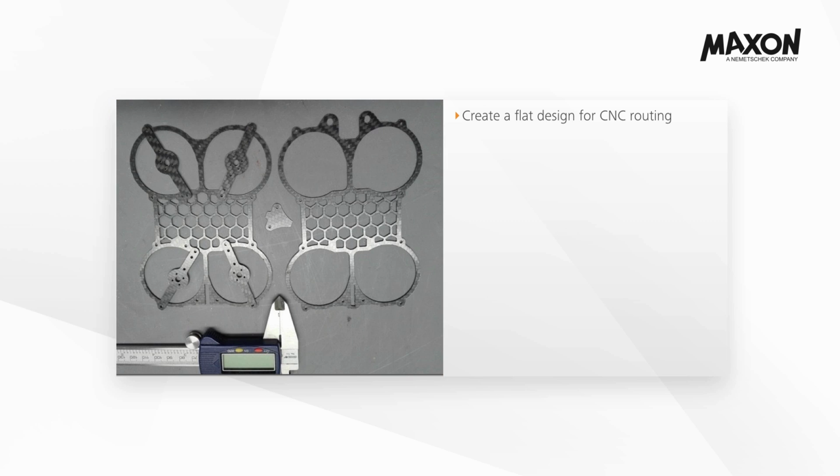So all my frames are made out of carbon fiber sheets, since it is a very durable material, and I contacted several companies to see what a CNC frame would end up costing and what file format they required. And luckily I could use the same 3D model I constructed in Cinema 4D and that I used for 3D printing to export a DXF file that was accepted by the milling machine.